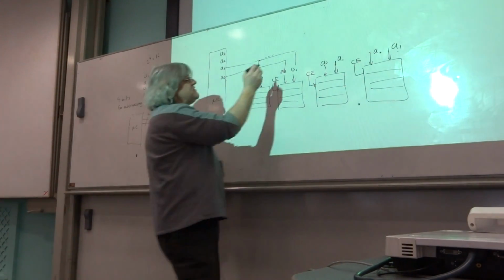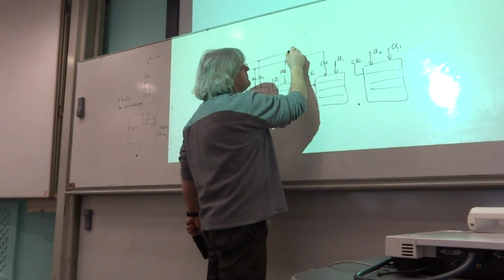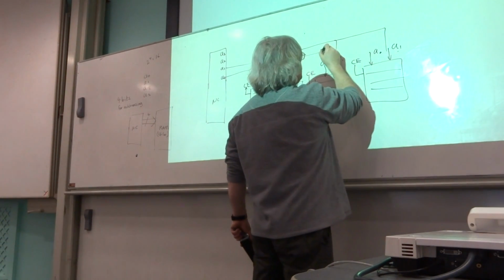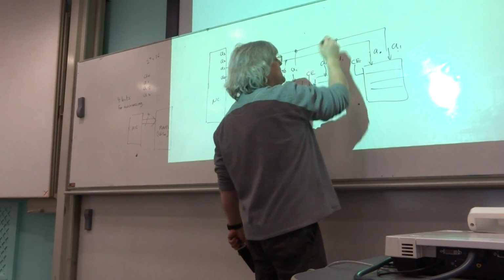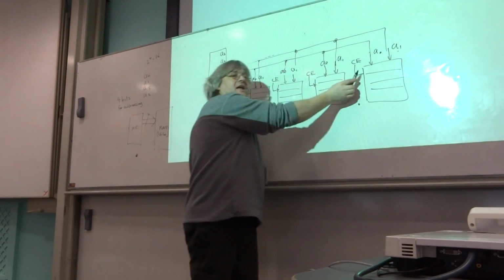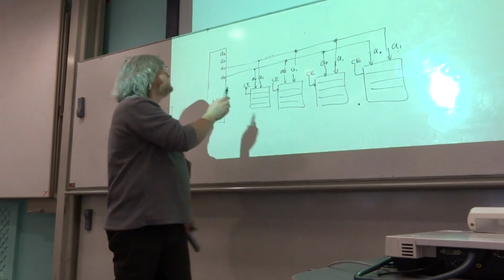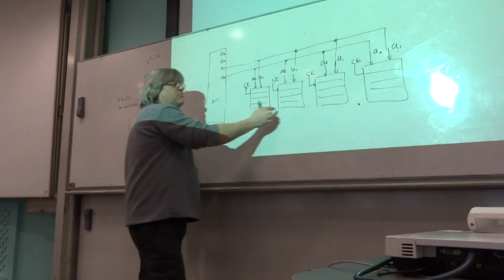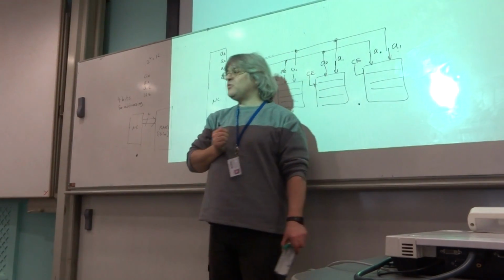So what I could now do is wire this up like this, but use these other lines connected somehow to these additional address lines here to make sure that at any point in time only one of these is awake.